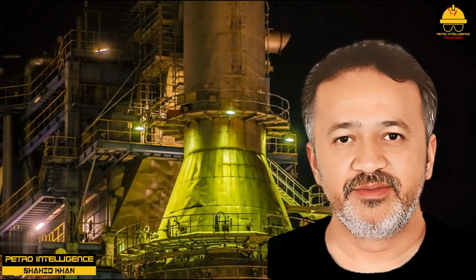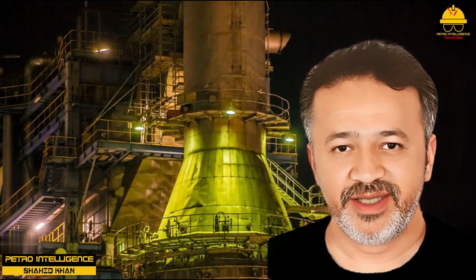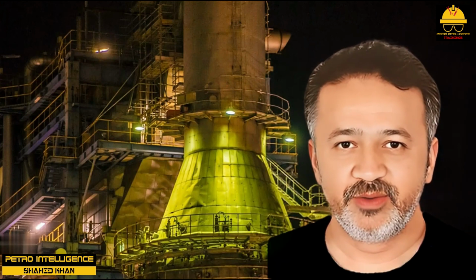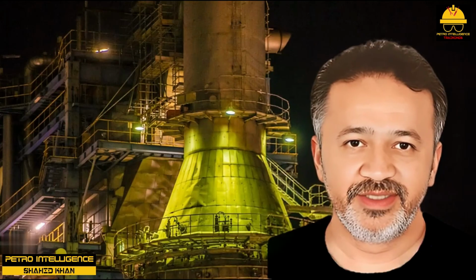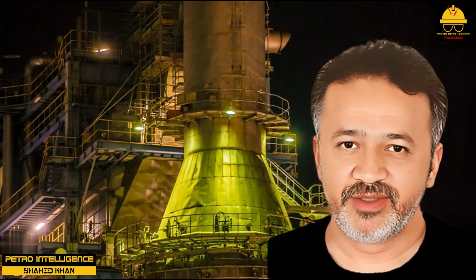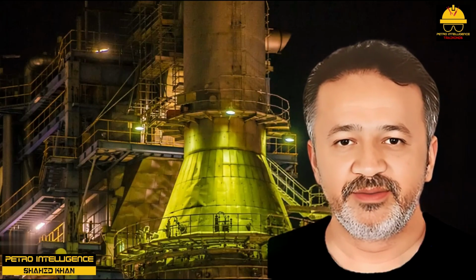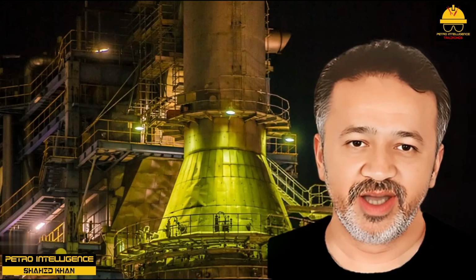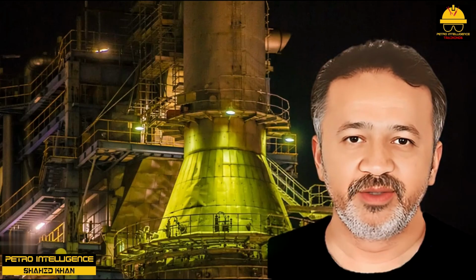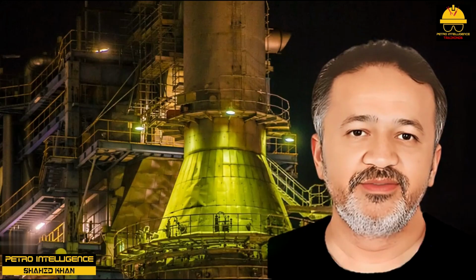Lack of air affects draft and combustion. Normally, opening the air registers at the base of a heater reduces draft, that is, increases pressure below the bottom row of convective tubes. This happens because the extra combustion air creates more flue gas, which results in an increased delta P across the convective section tubes and the stack damper. However, if the heater is operating in an oxygen-deficient environment, or it is running below the point of absolute combustion, draft will likely increase as the air registers are opened.